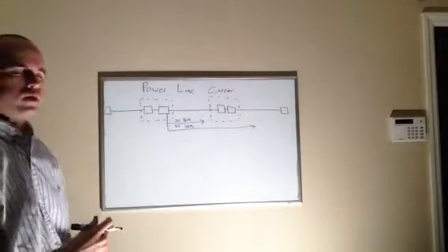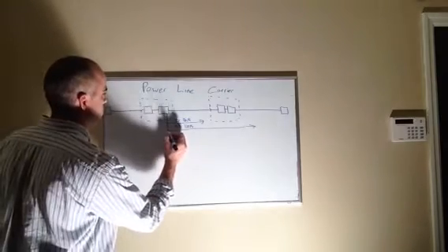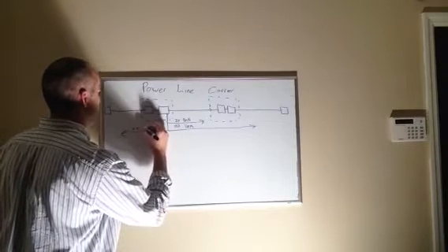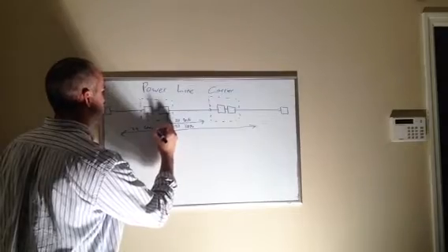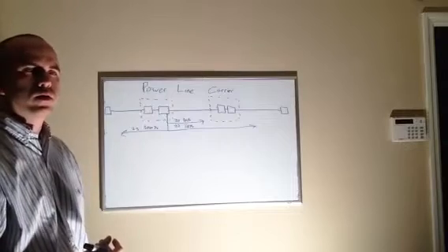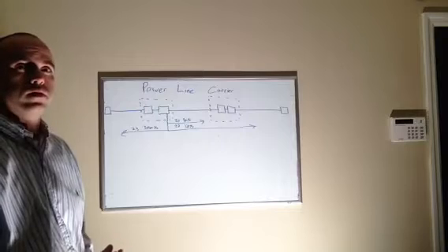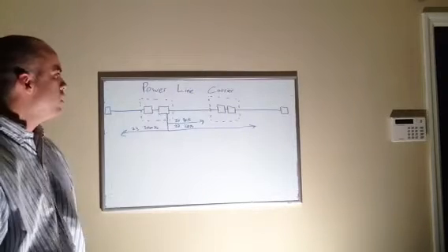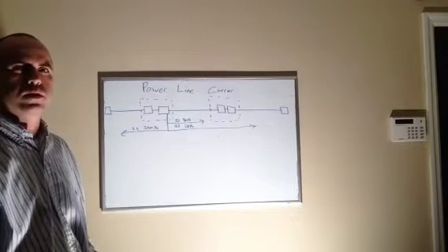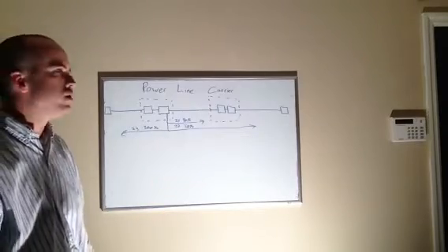Zone 3 is looking in the reverse direction, 300% or 3 line segments is a good rule of thumb. And by looking back that far, you would know that if you truly got a Zone 3 operation, it would be a huge deal, and it would be a widespread area outage. There are things that are implemented that we won't discuss right now, such as bus backups, that should operate to minimize the impact before you would have a Zone 3 operation.